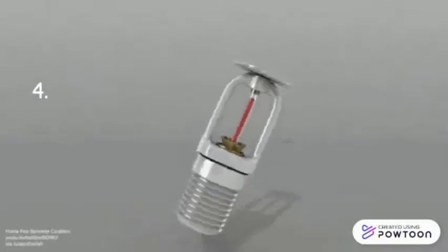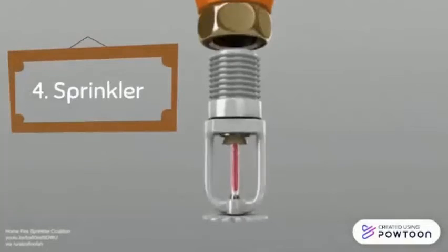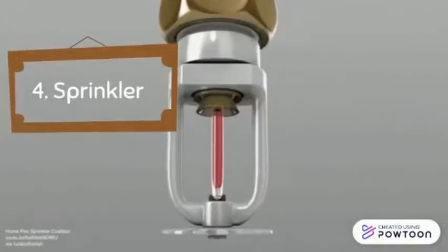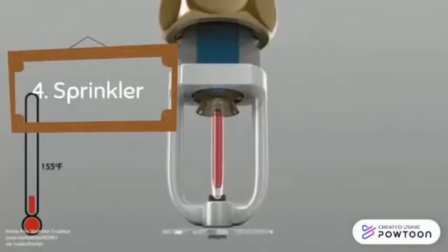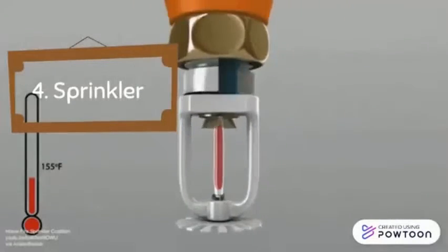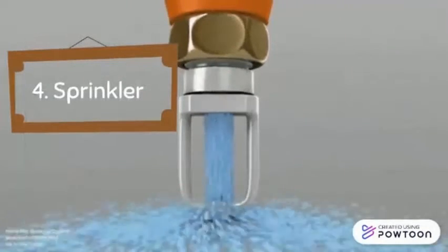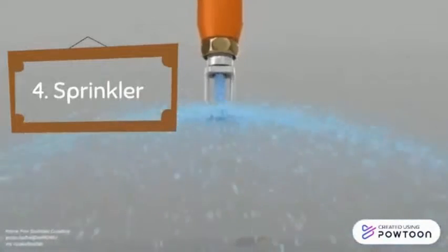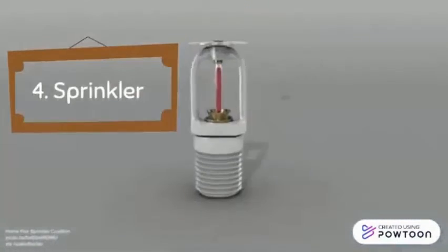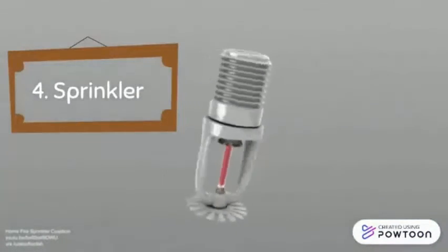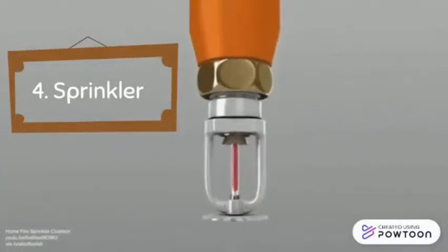Next, sprinkler. Sprinkler systems are intended to eliminate or reduce the spread of fire. It is a condition to install a sprinkler system when the building exceeds 7,000 cubic meters. Usually placed on the ceiling, it is a small device that shoots water down onto a deflector plate that directs a circular pattern of water over a fire in the structure wall.